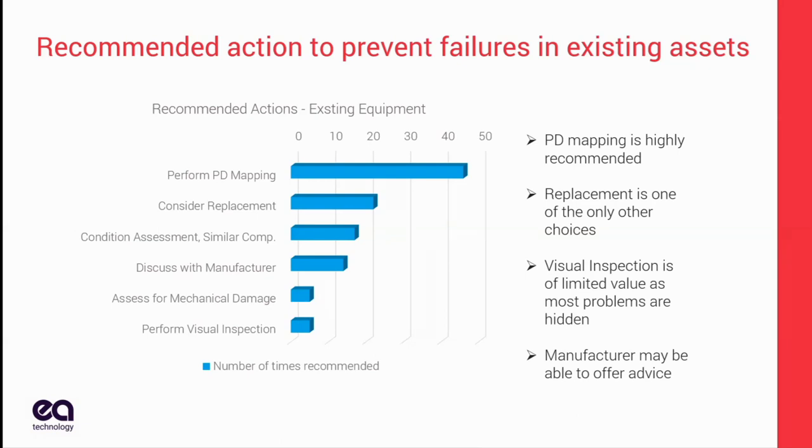You want to look at the condition of similar systems, similar cables, similar terminations. If I'm having a problem everywhere on the same type of termination, I can start doing some asset management and looking where I've got those terminations. Again, the manufacturer is one of your best allies, and visual inspections of terminations will show that surface discharge. So that's a really good thing to look for.